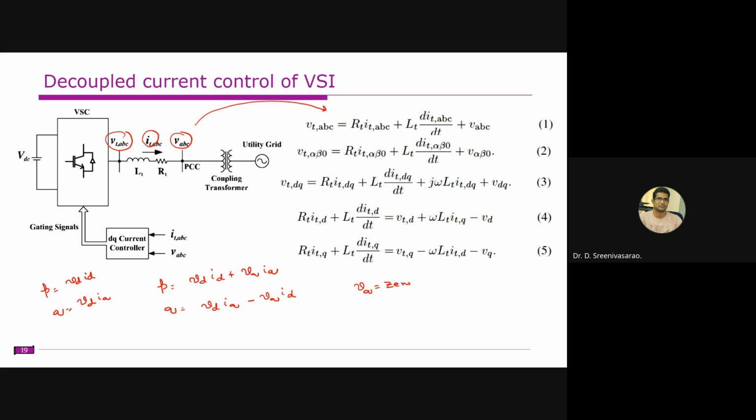Right. So the meaning is that if you want to control this P, for example, I want to inject a certain amount of power, say 10 kilowatt, so MPPT is observed that you are able to inject 10 kilowatt of power into the grid. That means your P star is equal to, for example, 10 kilowatt. Accordingly, you need to calculate the ID star. From this relation, this ID star is equal to P star divided by this VD. So that gives you the ID current.